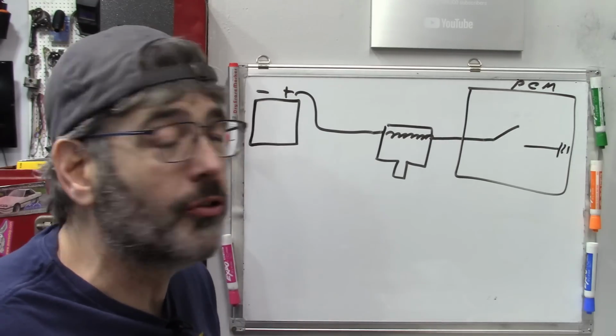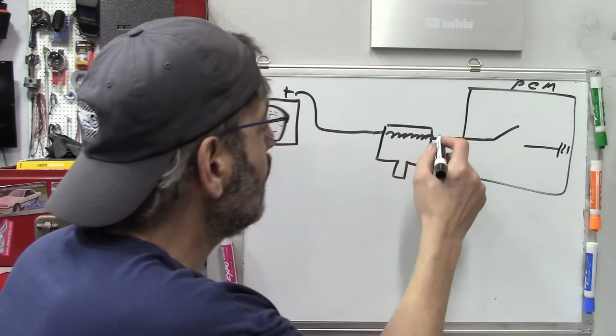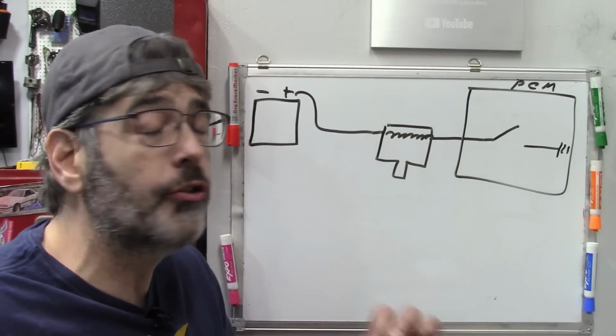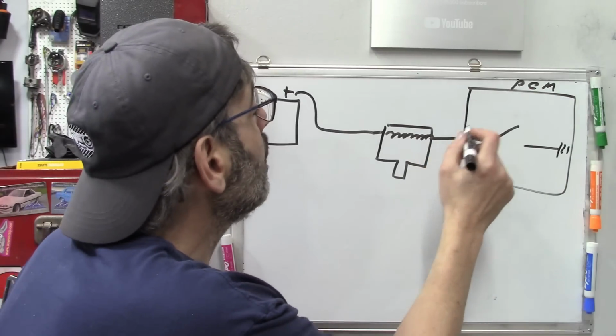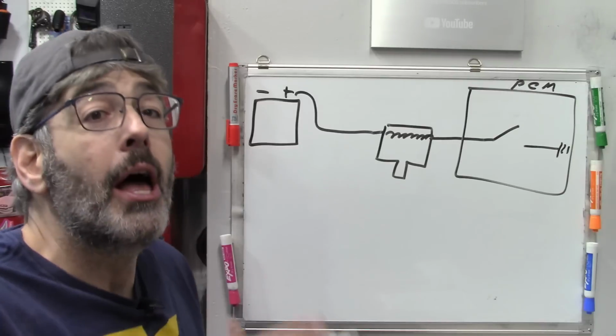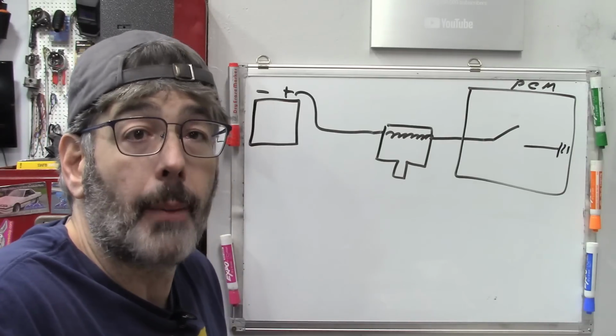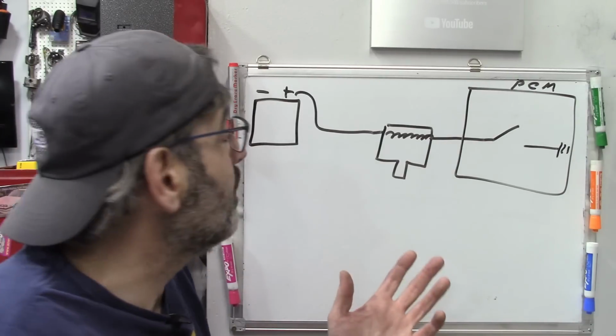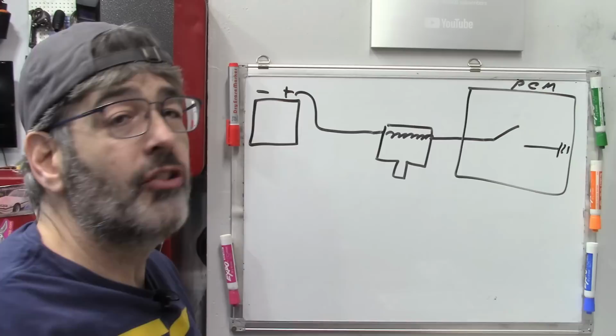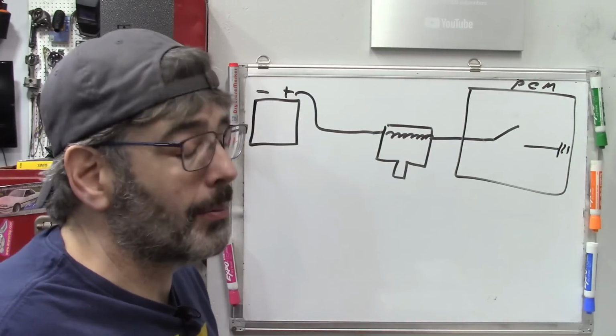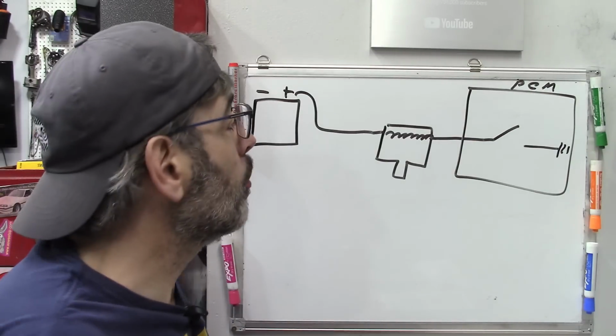There was always method to my madness here. The reason is because you have to understand where the voltages are going to change, because that's where you would have to hook up your picoscope or whatever your measuring device is. If you did not understand that concept, you are probably not going to set up correctly.